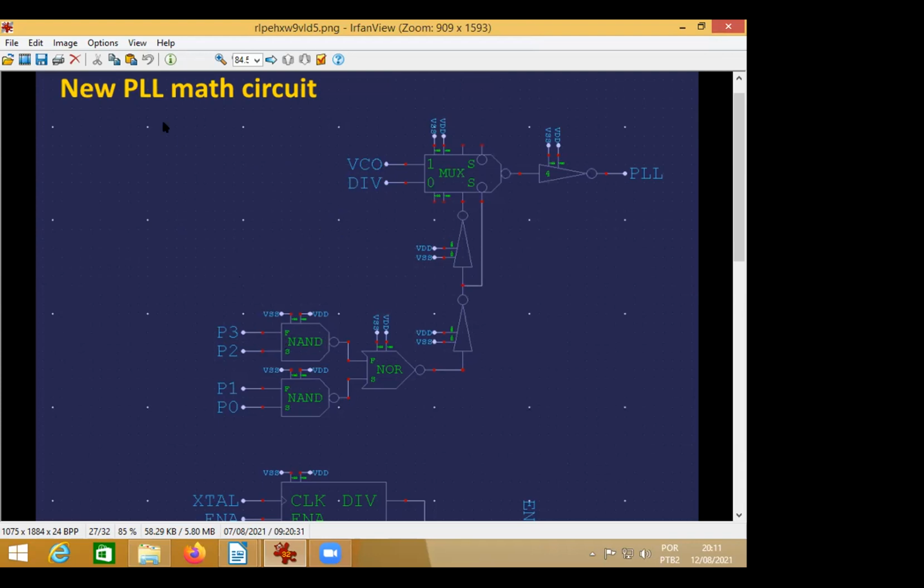One input is from the earlier stage, another input is the VCO, and the third input is div. And I block the VCO, or enable it only when I know, reading the CT, that the divider counter will maintain its output as 1 for more than 2 or 3 cycles of the VCO.